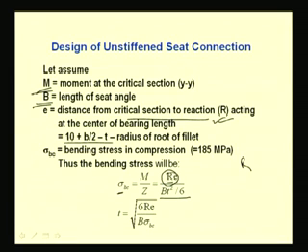Generally we keep this as 10 mm. So E will become 10 plus B by 2 minus T minus radius of fillet. Accordingly E can be calculated. And sigma BC is the bending stress in compression, which is generally 185 MPa.